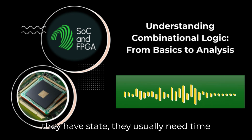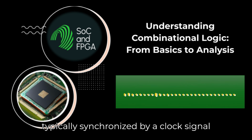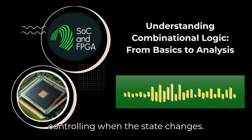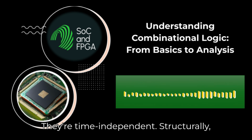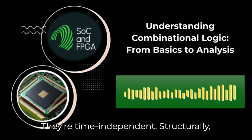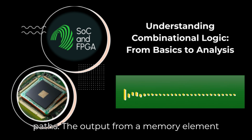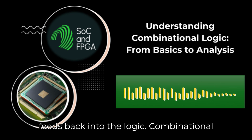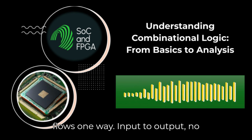Totally. And because they have state, they usually need time dependency. Sequential circuits are typically synchronized by a clock signal, controlling when the state changes. Combinational circuits, no clock needed, they're time independent. Structurally, sequential circuits also use feedback paths. The output from a memory element feeds back into the logic. Combinational circuits are strictly feed-forward. Data flows one way, input to output, no looping back.